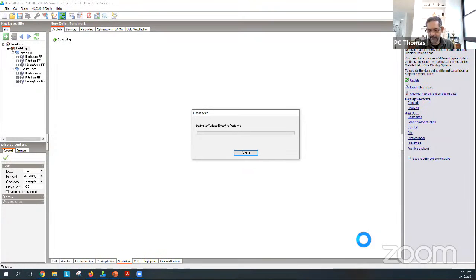I'm only running the month of March, so it's a short run. From the 1st to the 31st, we've got completely uninsulated walls, and I think I've got very simple single glass aluminium frame windows, which we'll do immediately after this, and we'll see what's coming out. I'll save these runs as well, so when we make some adjustments, we can see what's going on.